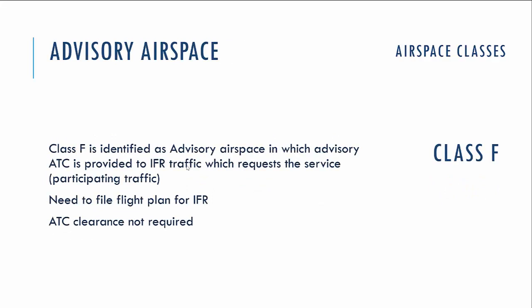Advisory airspace is a class of airspace in between the controlled and uncontrolled airspace. It is identified as advisory, in which the advisory ATC service is provided only to IFR traffic. And so you need to file a flight plan for IFR only, and ATC clearance is not required. Actually, class F now is not commonly used. At least there is no class F in Europe, in the European Union, and in the UK.